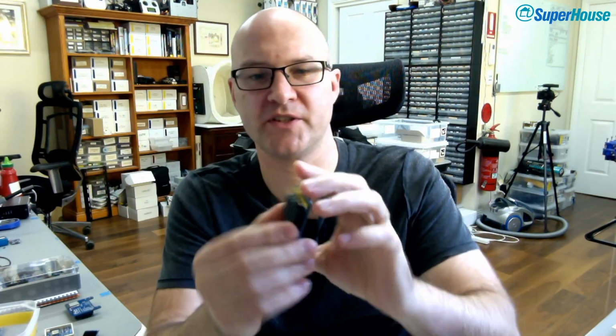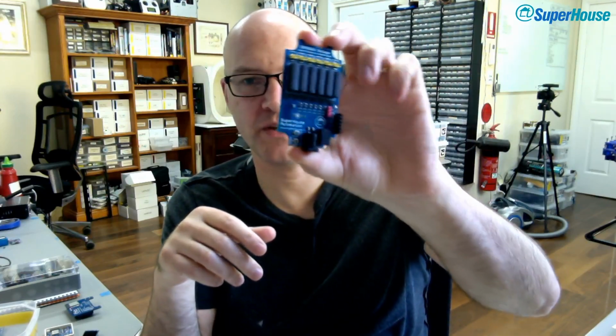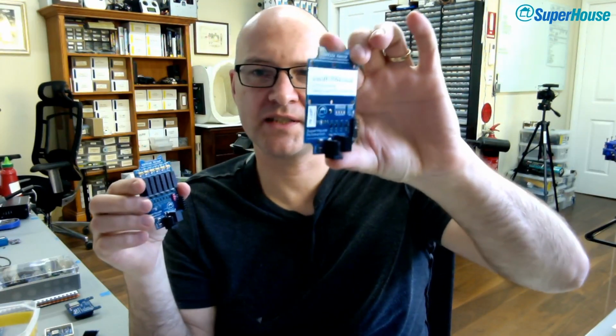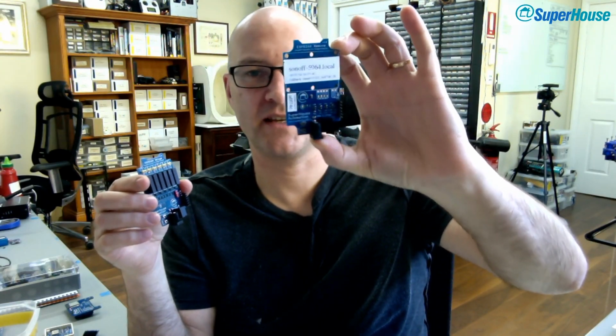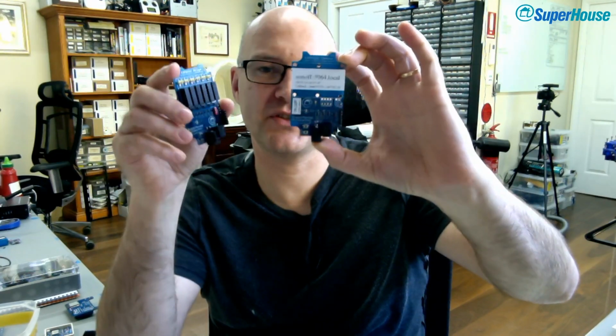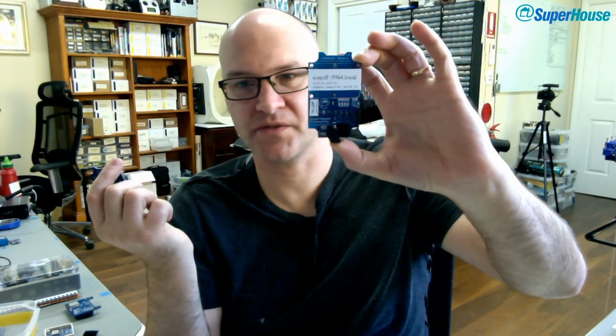Now, this particular project is something that I haven't shown in a video, but this is also one that will be in a future video. There are two versions of it. There is this one. This is a board that you can use to take any, it's basically a universal Wi-Fi interface for remote controls for devices. Like think about a garage door or something like that. What you can do is take the PCB out of your garage door remote control and cable tie it through the holes in the PCB so it's stuck in place on here. And then you can jumper across from the buttons on the remote control to contacts on here.